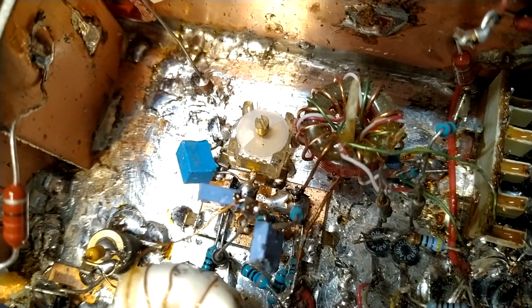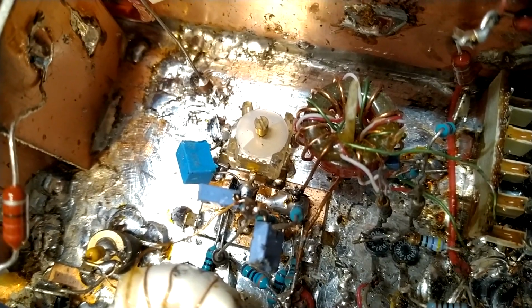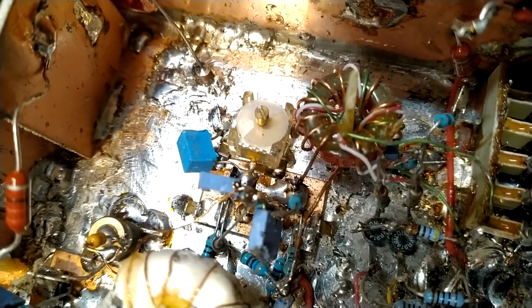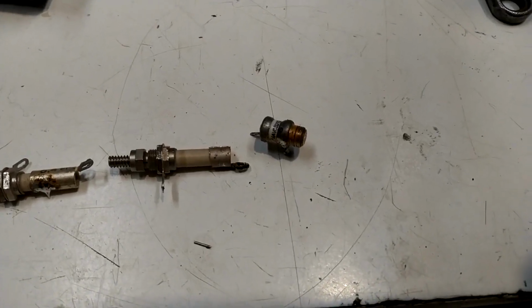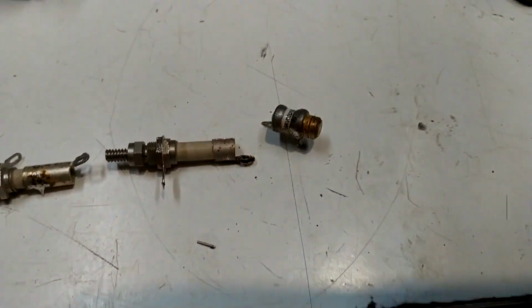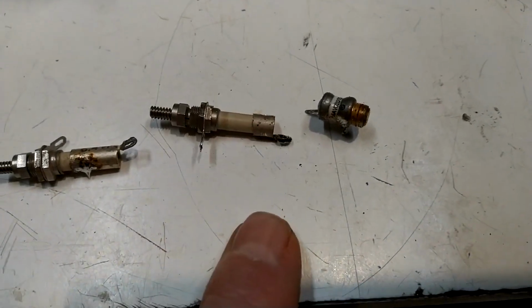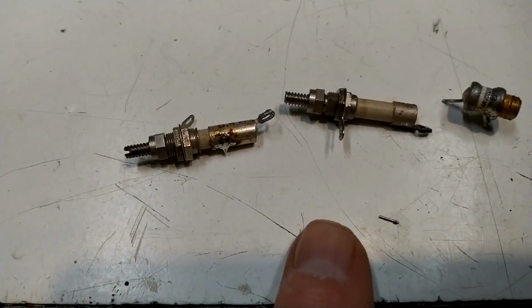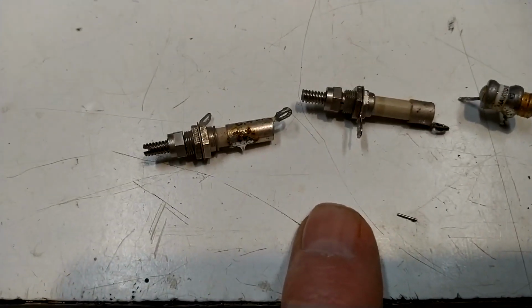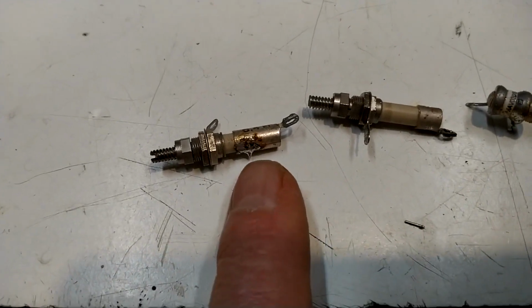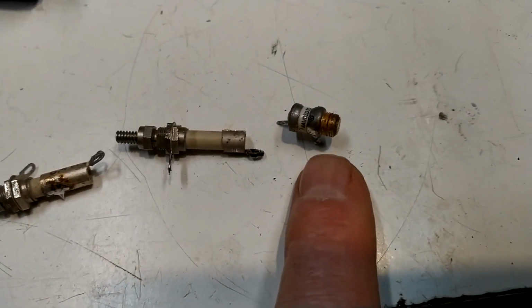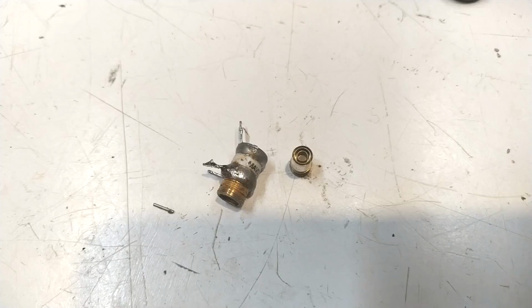When I open the box, I find that I have used one of the Teflon insulated trimmers. I will replace that. I will also replace this trimmer by this one, which is a modified version of this one, which had a too large zero capacitance, nominally 6.4 pF, but I need about half a pF or maximum 1 pF.